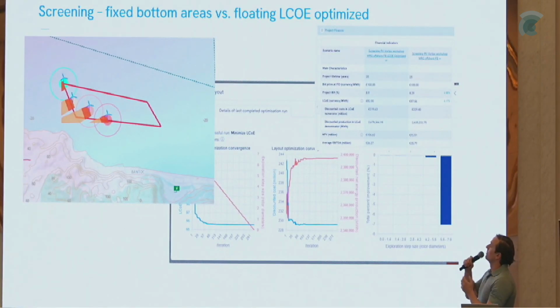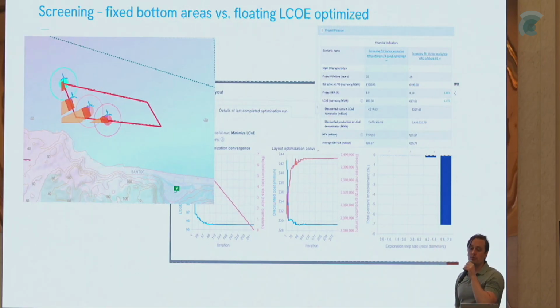So we're going to look at 4 different turbines. We're going to run the LCOE optimizer, and we're going to look at how much it costs. If you look at the LCOE perspective, if I just place the 4 turbines here, I connect them to the grid point, and what happens if I do the optimization? Same here, LCOE 87 to 82, so a relative increase in the yield. But you can see here also how the turbines are placed. So not in the center, because by looking at the windrows and at the exact grid point, you have the gross production, but also the net production when you're running it through the wake models.